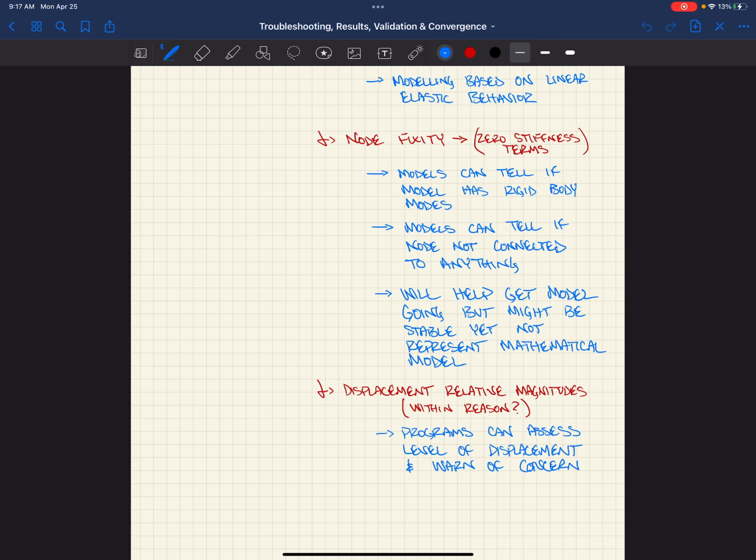Yes. If you have a pin connection and you have a member framing into it, would it be redundant to release that member framing into that pin if it's already pinned in place? Yeah, I mean, if you do that and that node doesn't have any other members attached to it, then it'd be unstable. So one of those members framing into that node will have to be able to actually hold the node. But I guess then there's nothing wrong with still releasing it or having it rigid. That's not going to affect the results.